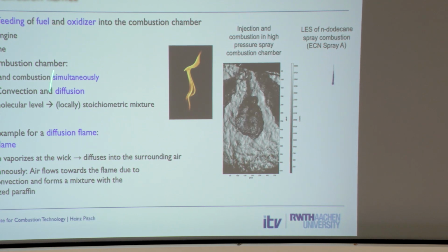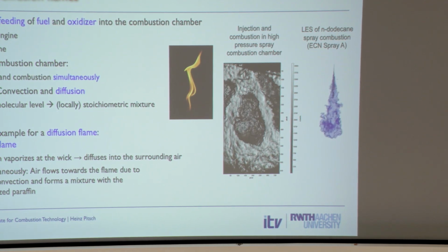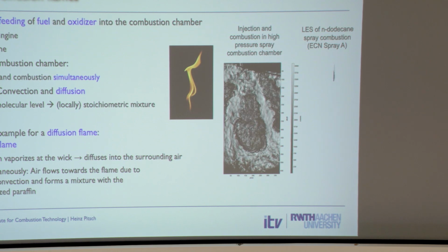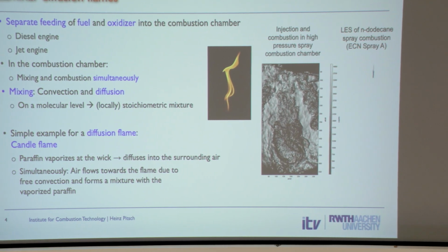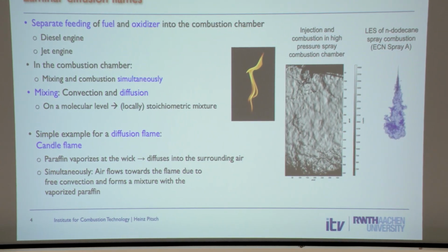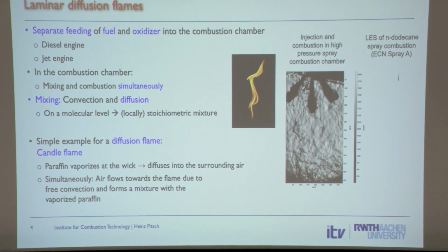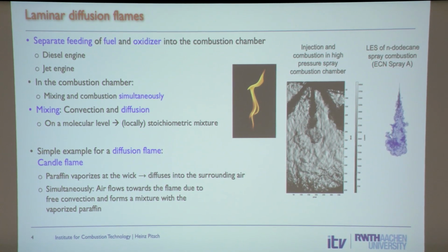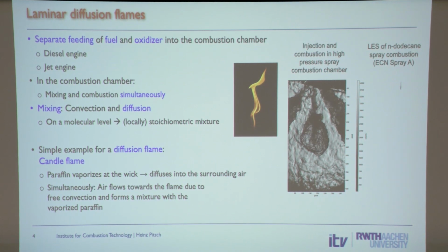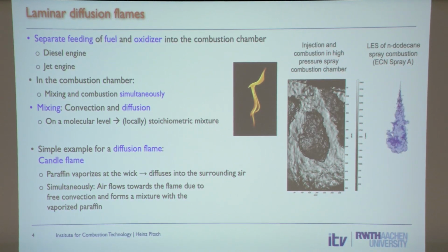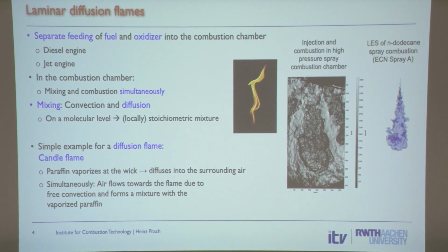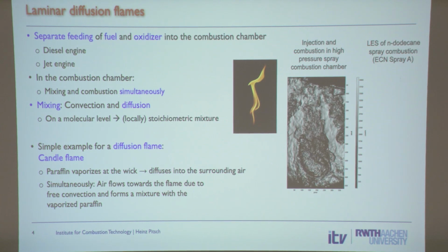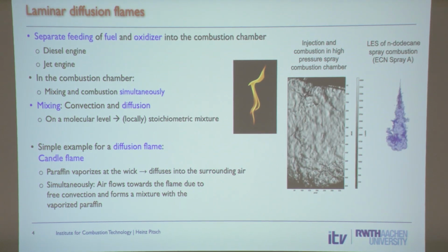So there are different cases where you technically use non-premixed combustion. We said premixed combustion is good for avoiding emissions, and that's usually what we want. But in a diesel engine, we use non-premixed combustion. Why? Because diesel engines have a nice feature. You might know this, but a spark ignition engine has a certain efficiency that depends on the compression ratio, and it's a constant volume process. The diesel engine is modeled with a different process. Thermodynamically, it's constant volume and then constant pressure, a combination of both.